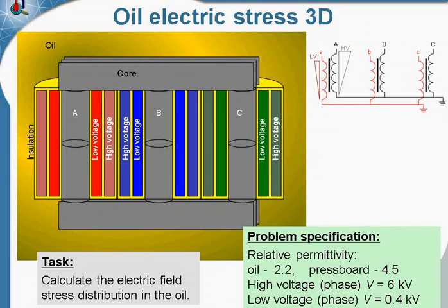Oil electric stress 3D. In the previous example we simulated a two-dimensional problem and calculated the electric stress distribution in the oil gaps near the end of the winding. In this example we will build a three-dimensional model and calculate the electrical stress in the transformer oil.